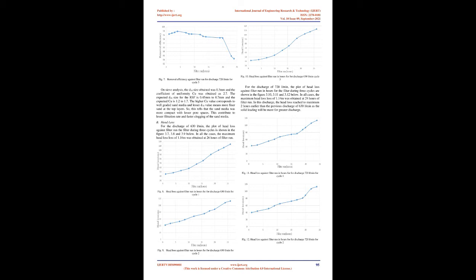Test procedure. The test procedure was followed for each discharge taken in consideration during the experiment. Turbidity measurement. Turbidity was measured in NTU. Turbidity measurement procedure was: first, the instrument was set on and left for stabilization at least for 30 minutes. The instrument was set to 0 using distilled water and then it was calibrated up to 100 using standard 100